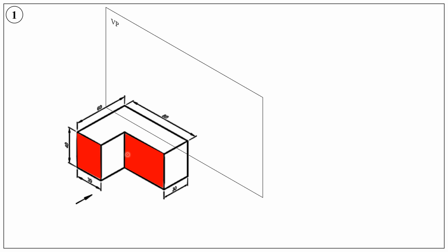So how to project? Draw perpendicular projectors from each and every corner point until those projectors intersect the vertical plane of projection VP. This one and this one are shown as dotted because they are invisible.